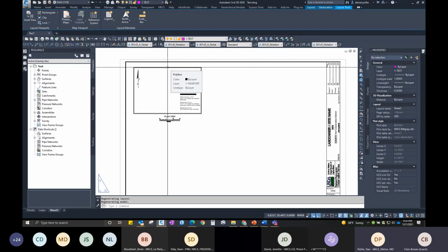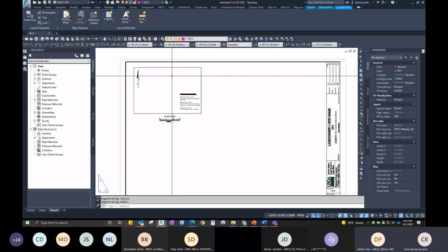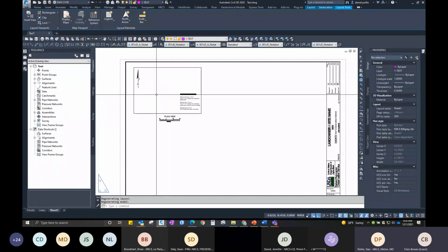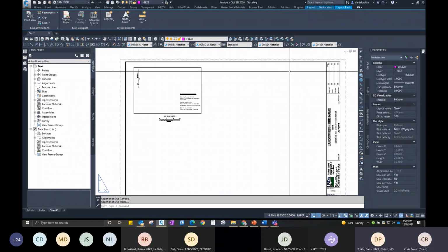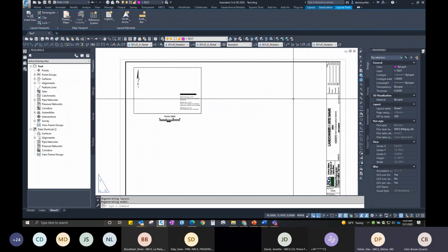But there are multiple times where you have a complex ag waste structure, for example, with a tank shown here and a roofed HUA over here, and you might have to blow these viewports up, meaning you expand them to a closer view. It might be 1:10 scale, because it's 2 acres of area and you can't see that, so you need to zoom in. Well, if all your text is 1:50 in this instance, and you needed to blow this up to 1:10, you're going to have to move all that text around, if that makes sense.